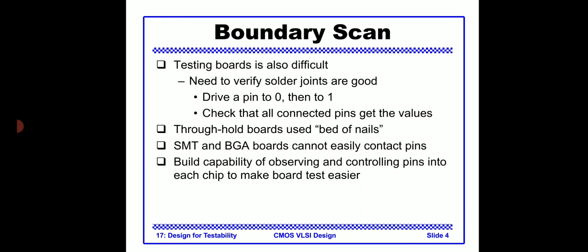Four primary factors must be considered in developing BIST for an embedded system: fault coverage, test set size, hardware overhead and performance overhead. The issues present in BIST are area overhead, since there is additional active area for the test controller, pattern generator and response evaluator, as well as pin overhead and performance overhead. Then there will be some loss in yield. Next, the design will be more complex and the design time may increase. So these are the things to consider in BIST.